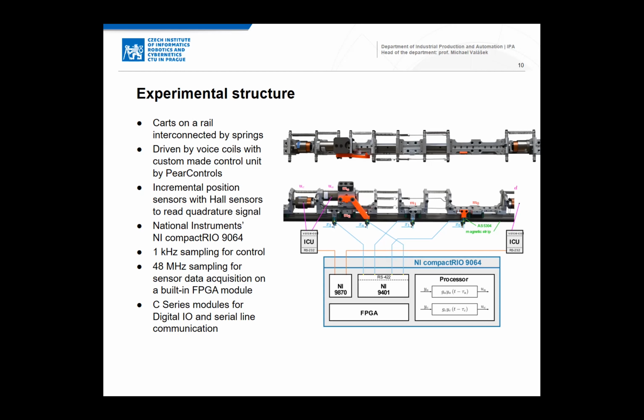It's implemented in LabVIEW and it runs on an industrial controller, here specifically the CompactRIO 94, which has several slots for inserting modules, which extend the connectivity of the controller. Plus, it has an integrated FPGA, which we use for sensor measurements.